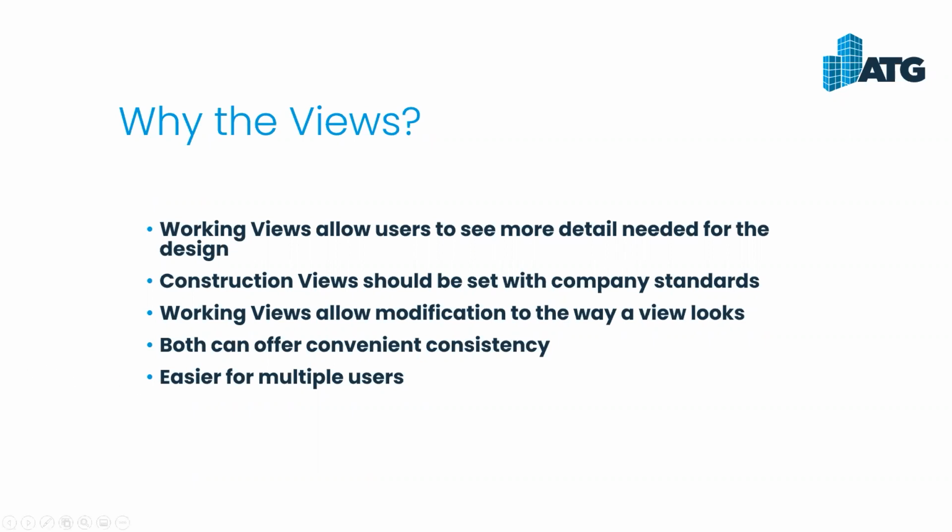The other thing is that with both the construction and the working type views, they can offer convenient consistency. What I mean is that you have that consistency from project to project. With your construction views, when you have your view templates assigned, you know it's going to look correct. I can't say about the design.